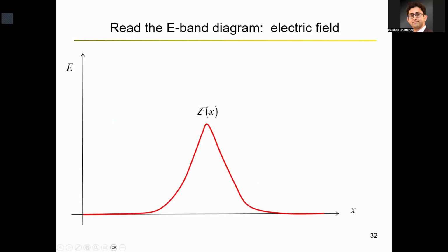So near the PN junction, you'll have a non-zero electric field. Everywhere else you'll have a zero electric field. We didn't talk about this much, but it's something that is impressed upon a lot in device physics: you do not have an electric field toward the beginning or the end of the PN junction structure, but only near the actual junction where you are switching from a P-type semiconductor to an N-type semiconductor. Near that actual junction, you'll have electric field.